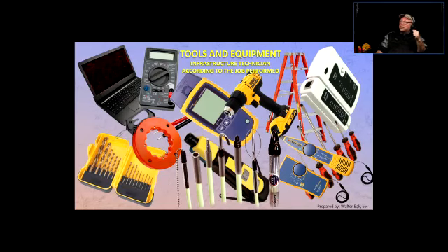Now, I might encourage you to get a hammer drill, right? And they will be cordless hammer drills. What's the difference between a hammer drill and just a regular drill? The regular drill just gives you the rotary motion, okay? It's just to drive the drill bit and turn it around. When it comes to a hammer drill, it not only makes things spin around, but it gives a repetitive vibratory type of impact. So it's as if you were hitting it with a hammer. That's why it's called a hammer drill.